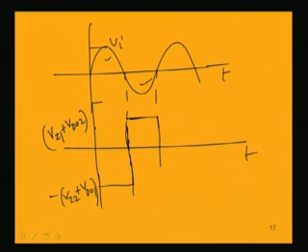We are getting a limited voltage, not V saturation, but it depends on VZ1 and VD0 for the two diodes. If we take a Zener diode having, say, 5.1 volt Zener and 0.7 volt as the diode drop, we can get 5.1 plus 0.7, around 5.8 volt, not the 14 volt V saturation that we were getting.